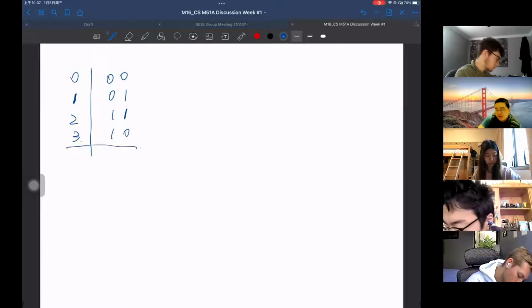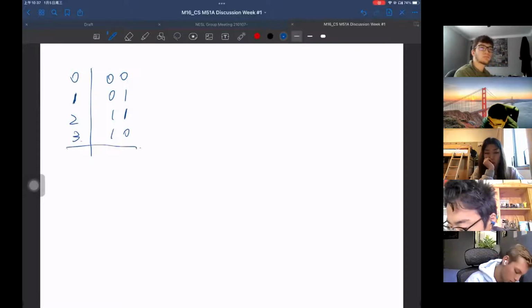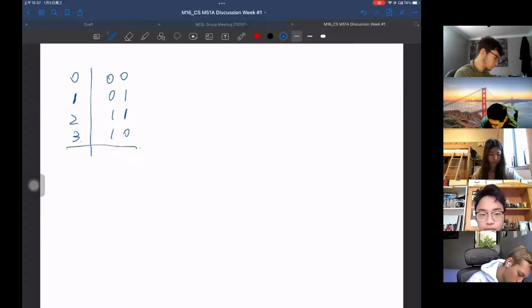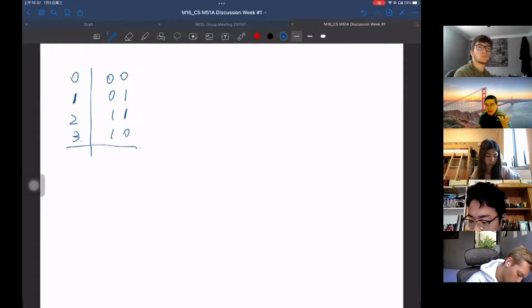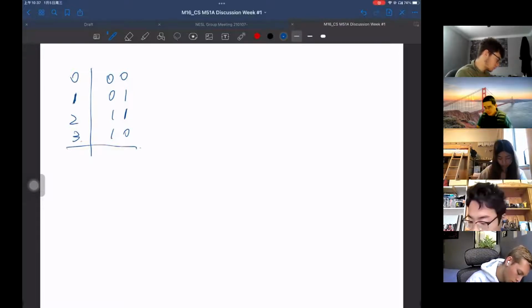So any thoughts for 3 bits? Just to give you information, Gray codes are not unique, which means you can have different rules to create different ones. The order is not unique, because we have 8 codes and they are all used, but the order can change.